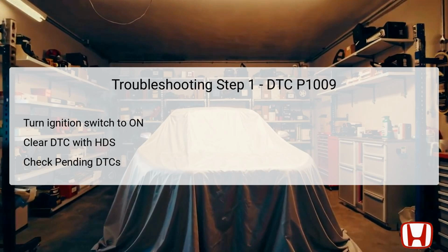After clearing the DTCs, proceed to start the engine and check for any pending or confirmed DTCs again using the HDS. If DTC P1009 appears again, it indicates a persisting issue requiring further investigation. If not, this may suggest an intermittent fault within the VTC system, which can sometimes resolve itself without further action.